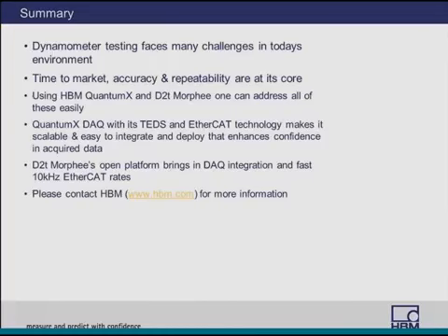The only thing is today we can communicate directly with the ECU. So that means the ECU is usually running at up to 10 kilohertz, maybe more. So we need to communicate with that ECU very fast. Also, we have other applications such as the simulation or the models which are running at a very high frequency. So in order for those models to perform fine, we want to run at a very high frequency, and that's why 100 Hz is not enough anymore in today's testing environment.